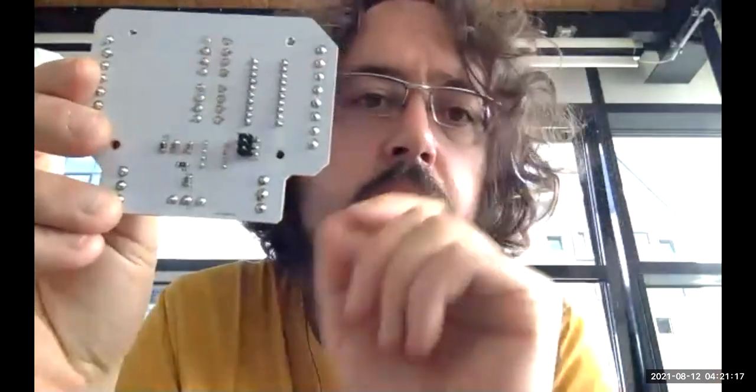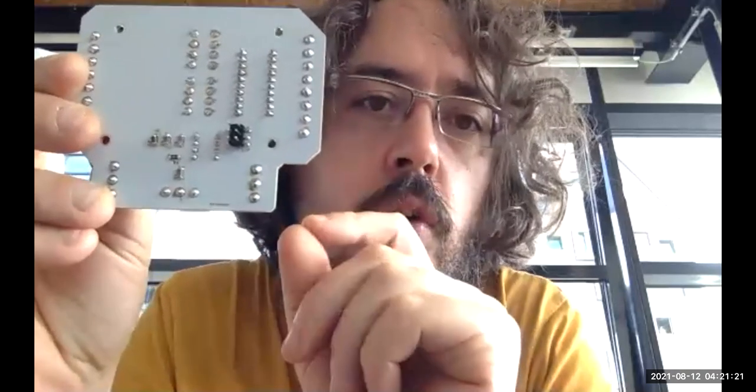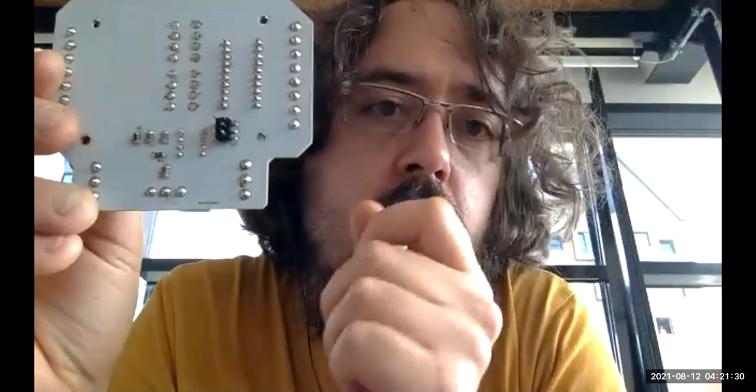First of all, you know that the signal output from the microcontroller is not going to be very strong. You're not going to have many milliamps in that signal. And secondly, sometimes you don't get the right voltage at which you need to operate the device. For example, in our case, the laser power supply works with a 5 volt signal.